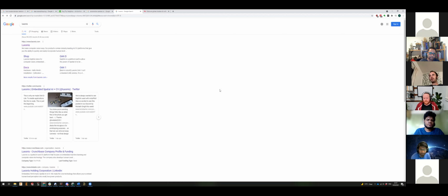Potentially in the rover application, if you know what you're looking for or have a pretty good idea, you can just correctly scale the sensor so you don't have this problem, and then on-sensor compute is super easy. But if you don't know what you're looking for, that's where you have issues. You can always do something like the fisheye, with a very large field of view, but then you run into that inherent resolution problem.